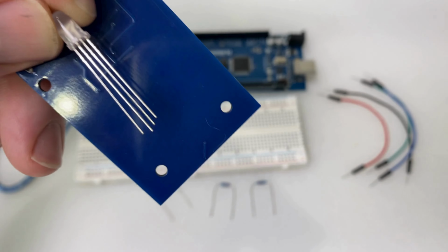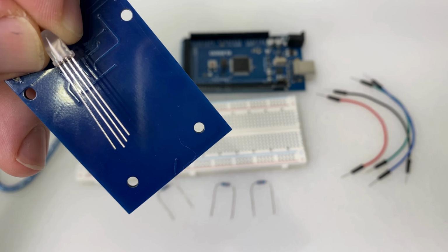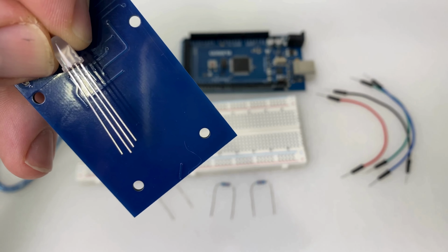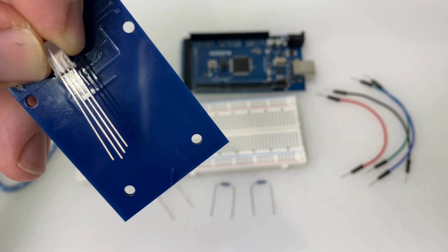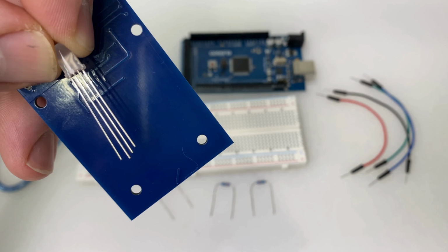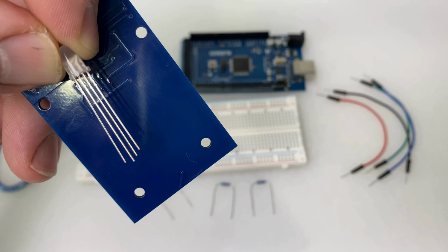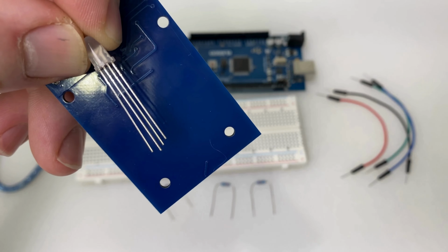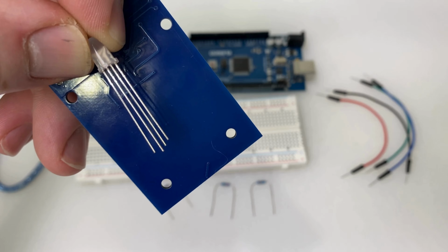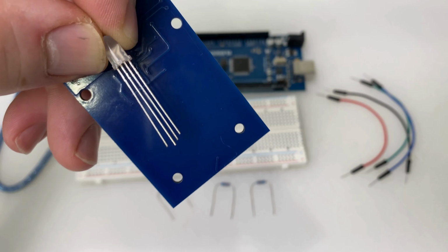If we take a look at the LED, that long pin there is the cathode, and the pin to the left of that is the red, and the pin to the right of that is green, and then to the right of that one, the far right pin is blue. So that's how we have to connect it on the board. So from left to right, it goes red, black, green, blue. We put that straight into the board now.